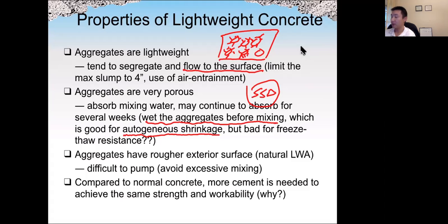But it is bad for freezing and thawing resistance, because when the lightweight aggregate is saturated with moisture and the temperature goes below zero, it will become ice. That damages the aggregate and then cracks the nearby cement paste. So it is bad for freeze-thaw resistance.